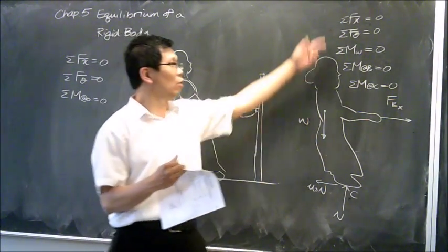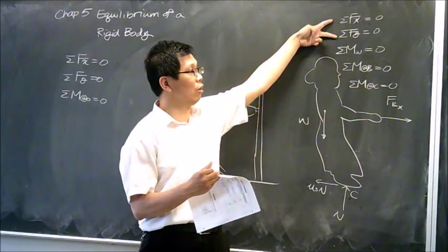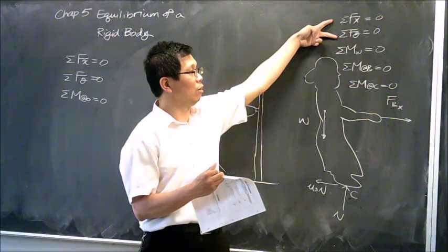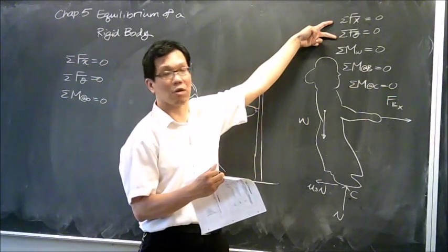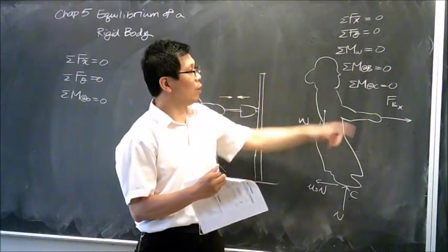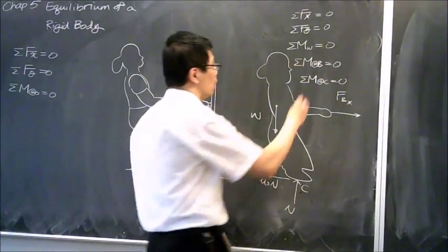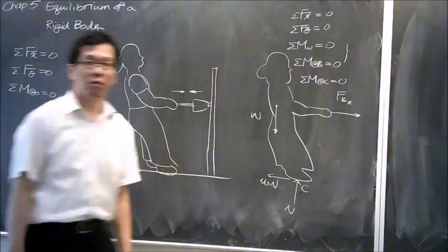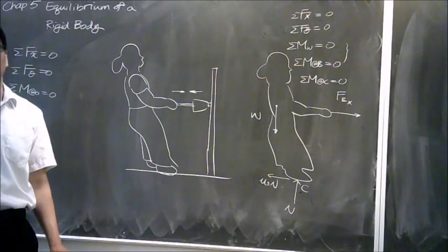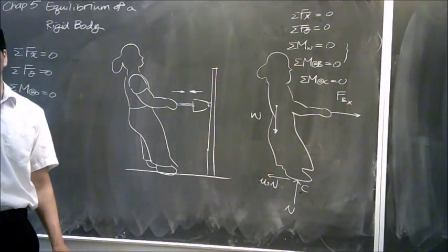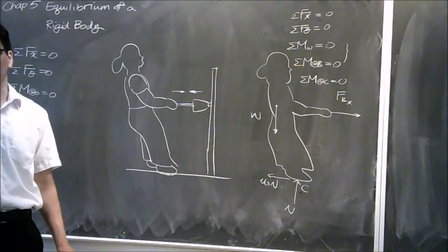In that case, we certainly want to use those two force equations, because there are no moment arms included in them, so we definitely want to use those two. But if you have an additional unknown in your system, you might want to use two moment equations. So in that case, you're going to have four equations to deal with four unknowns. That will somewhat simplify the calculation.